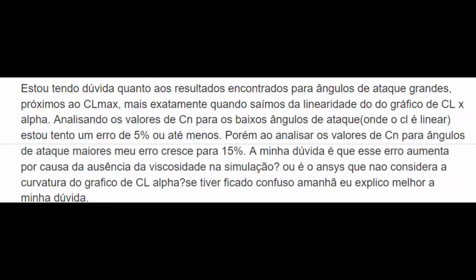This can happen because what we are simulating, for example, K epsilon or K omega model, is all based on averaged equations of Navier-Stokes. And it means that we do not see the oscillation, we do not see the perturbations of the flow, and all perturbations come into the equation as average values. So we cannot see a transient picture.